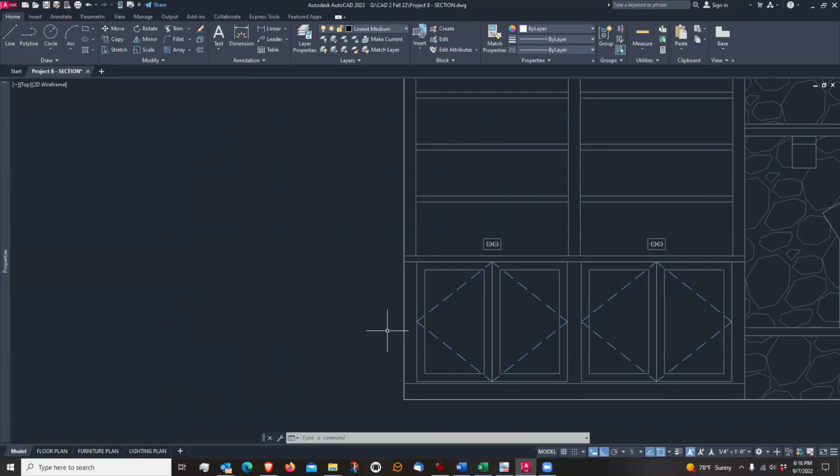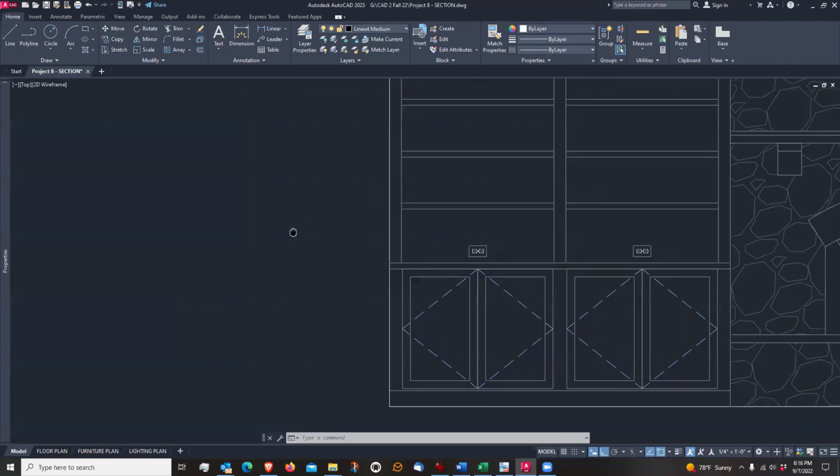So this will be wood studs with drywall on top of it. And so the first thing that we need to do is draw drywall. Drywall comes in a whole bunch of thicknesses: half-inch, quarter-inch, even eighth-inch drywall. If you have a barrel vault or something like that, your contractor will use a thinner drywall because it can curve easier. But we want a good, thick, sturdy drywall. So we're going to use 5/8 drywall, and that's the most common drywall thickness. So I'm just going to start by offsetting 5/8 of an inch to put that drywall in right there.